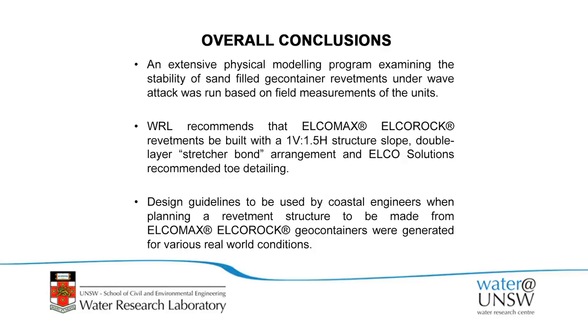We've published some design guidelines based on this output. It's been put in the last Australasian Coasts and Ports conference, as a paper that summarises all these design conditions for real world conditions. We tried to come up with quite practical guidelines where we simply put a wave height at the structure and wave period as the main things to think about, rather than some fairly esoteric inputs such as water velocity at the still water level.